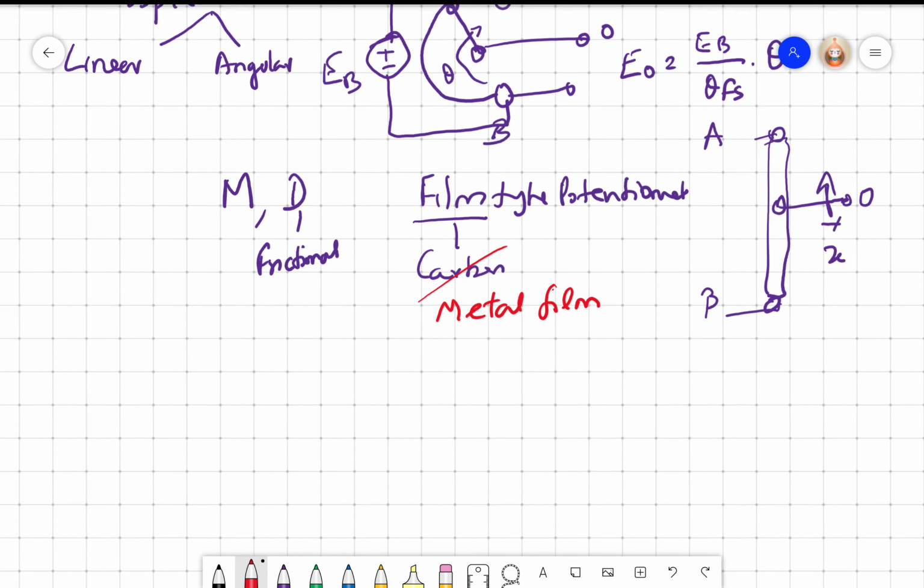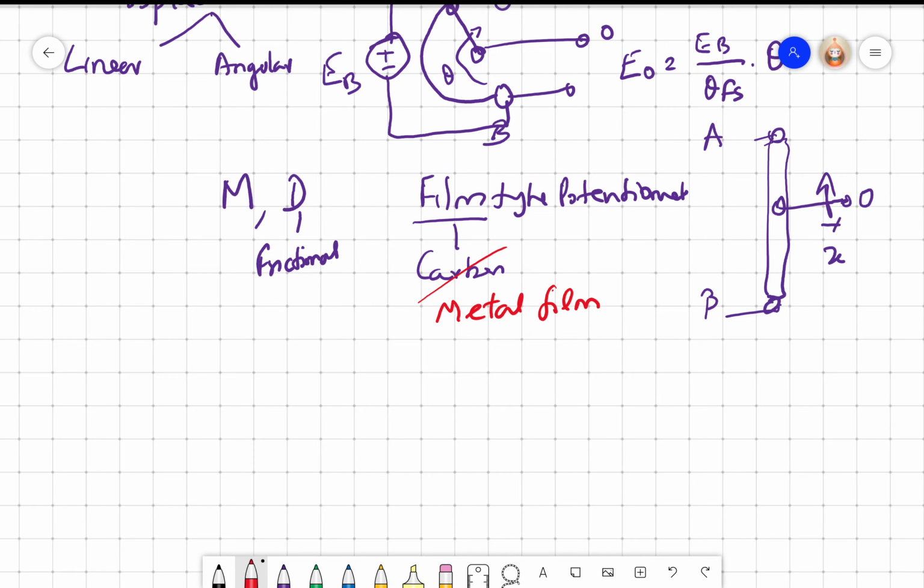Now, if I look at the electrical side, on the mechanical side, we already said there is M and D. So M in the electrical equivalent, I will get an inductance if I use the direct equivalent. D, I will get a resistance. On the electrical side, it's just resistance, nothing else.